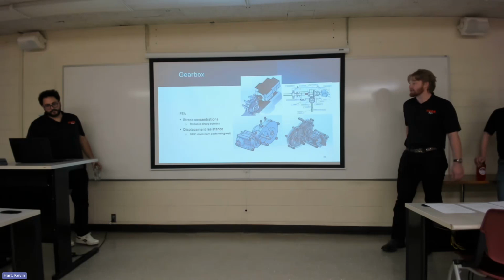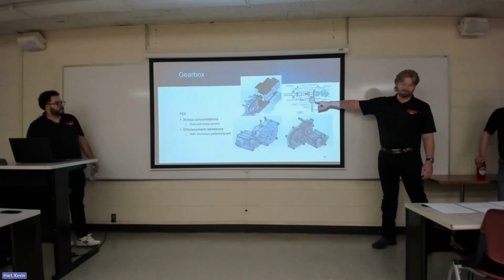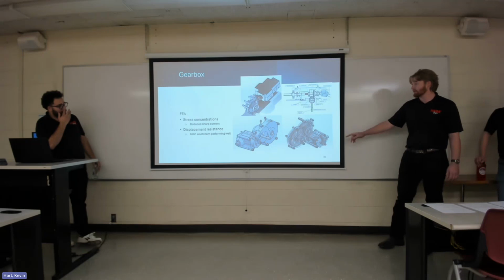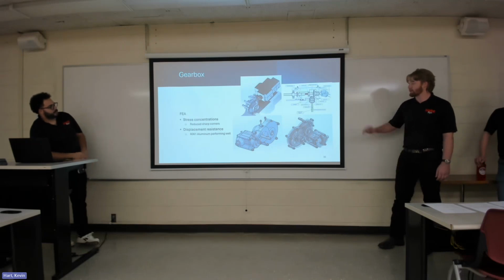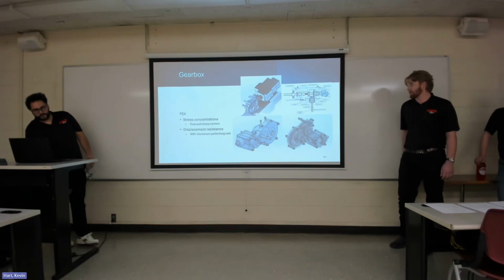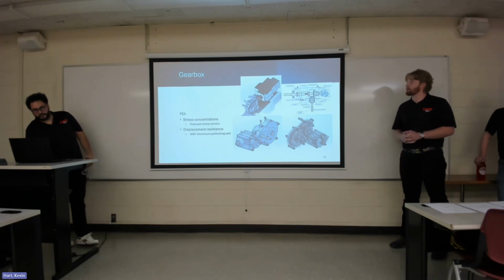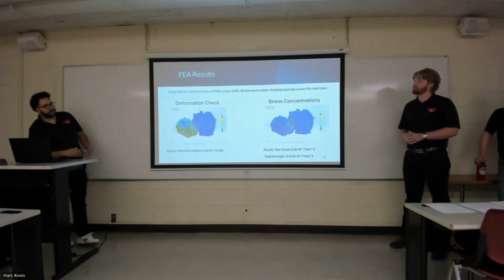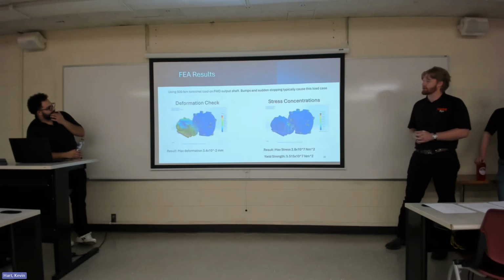And then I did some FEA on these, so some stress concentrations. Obviously, this box up here isn't very good for stress concentration, so we reduced a lot of those with some fillets and rounding around the gear profile. And then we did some displacement resistance, and the 6061 appears to be performing well. So these are just some initial FEA checks.